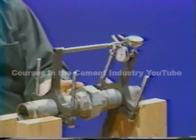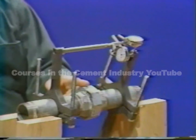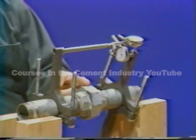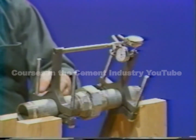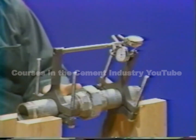This kit allows you to mount the dials on the shaft rather than directly on the coupling. This has a couple of advantages. First of all, you don't have to be concerned with the many shapes and sizes of couplings. Secondly, you can bolt the coupling together so both shafts turn together when taking readings.